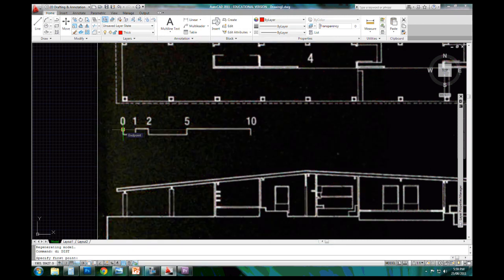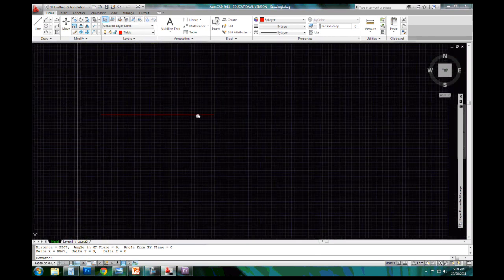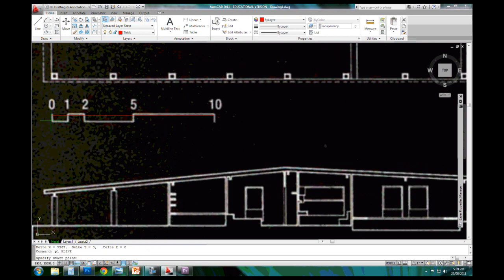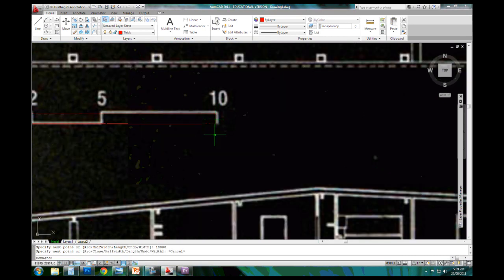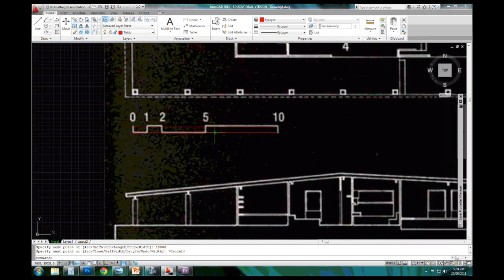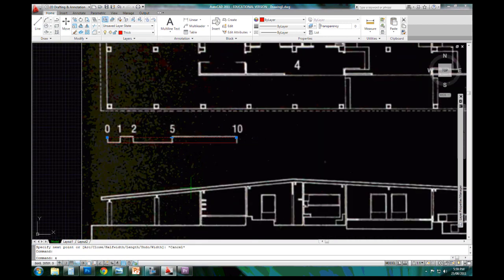I did use the distance command a little bit earlier to measure that line at 33. Now it should represent 10,000. It's nearly there. It's actually 9,967. But I'm pretty happy with that. The thing is that when you're zooming in on this, you do scale it back to 1:100. So just continually remember that you're actually working on a piece of paper. You can see that the line is there, and because there's a thickness to this line in the image, and you work predominantly with what they call hairlines, 9967 is close enough.